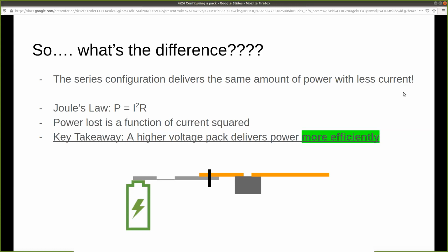At our first presentation 2 weeks ago, we talked about all of the different places there's resistance in the battery pack, whether that's the cell itself, the spot welded connections, the fusible links, any of our bus bars, bolted joints, components. All of those are carrying the pack's current. At any one of those locations, we're going to be wasting power based on this equation, current squared times resistance. So if we can reduce current, we very quickly gain back that power through efficiency because of this squared relationship.